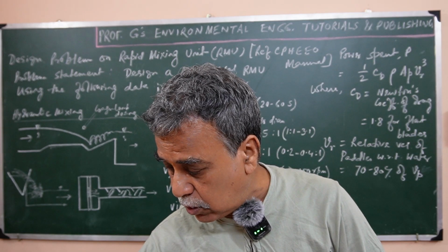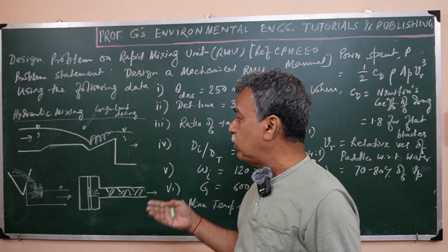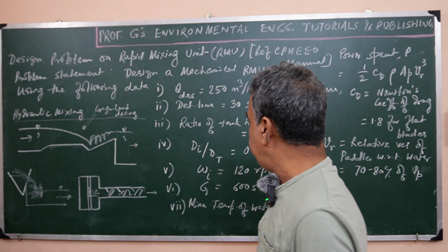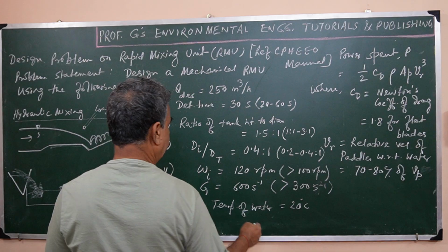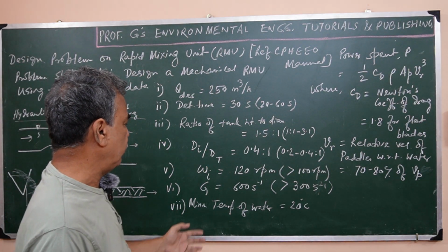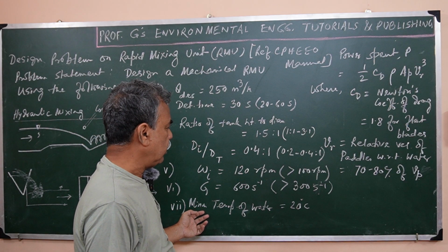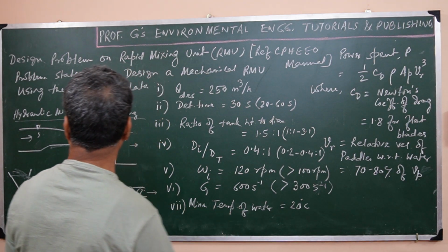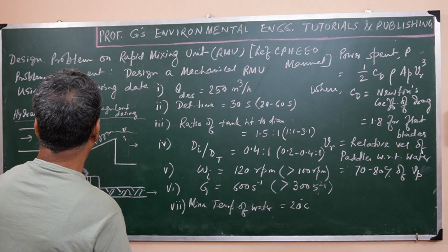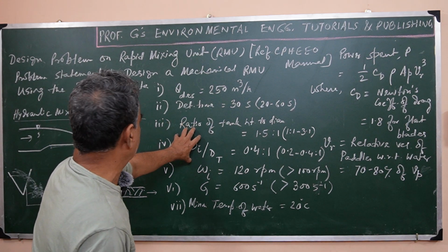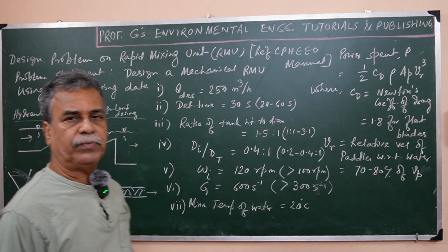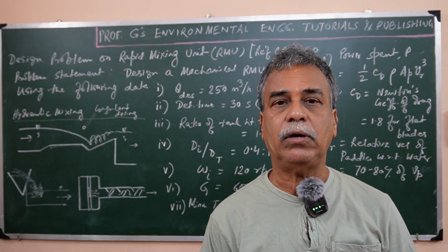As I told earlier in my last lecture session, the minimum temperature will give the maximum viscosity or maximum density also. So that is why we take the minimum temperature based on the statistical data of the last few years with regard to temperature, so that we can get the maximum viscosity or density. Now, before coming into this, let me quickly touch upon rapid mixing.